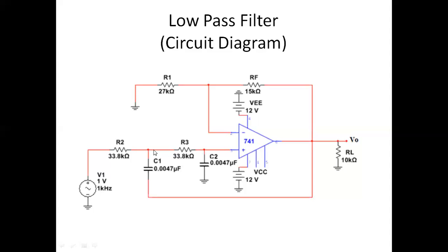For that, we have the resistor capacitor connection in this way. Now during low frequency, what we want is that the signal should be selected to the op-amp. So whatever input we are giving, nothing should be grounded, rather it should flow to the input of the op-amp. During low frequency, we know the reactance of the capacitor is very high.